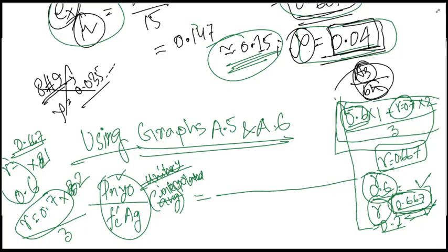So let's go to the graph. From this graph, in this particular direction, we don't have to be concerned about this one. Now we'll be concerned about this one, that is Pn by fc prime Ag. As we are concerned with the y direction, we will be getting this value for the y direction, about the y-axis. For the y-axis, we know we have an e by h value of, if you can remember, 0.15.